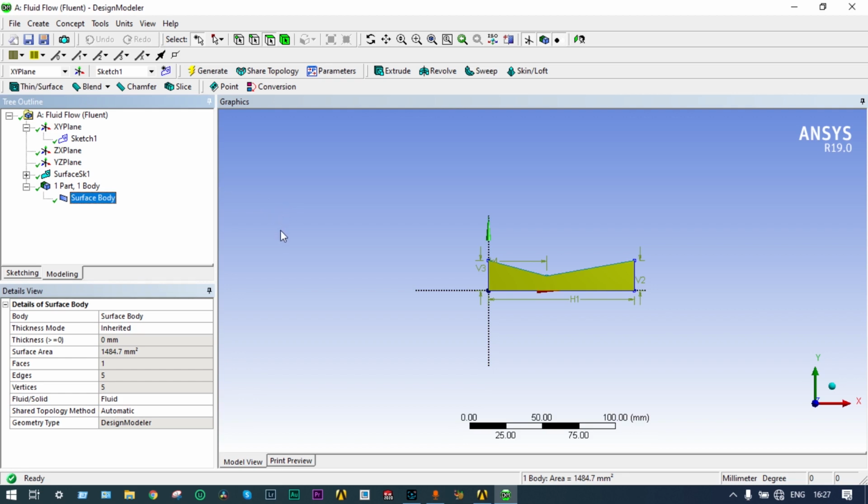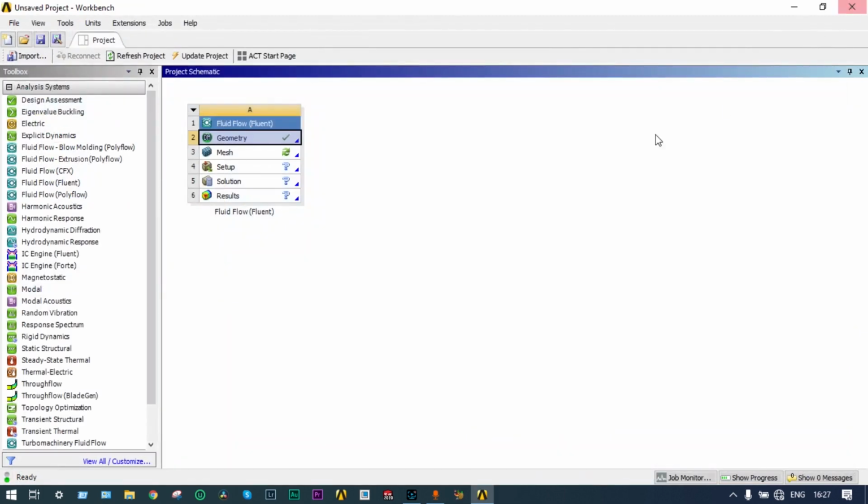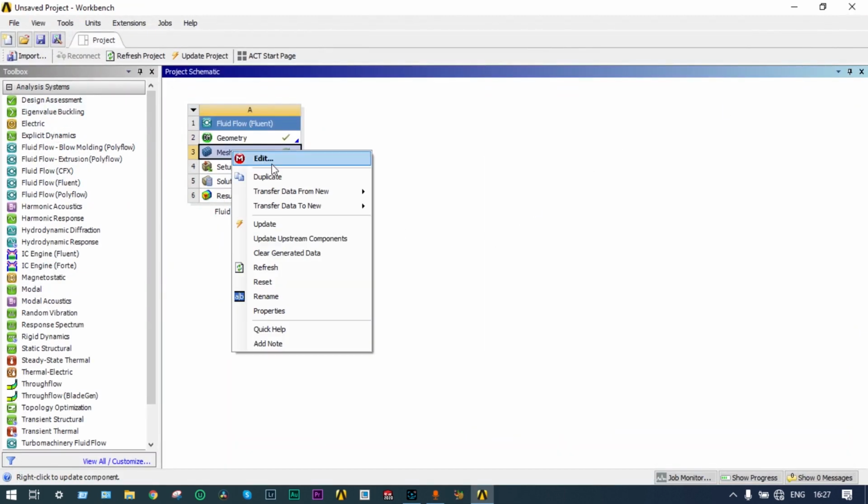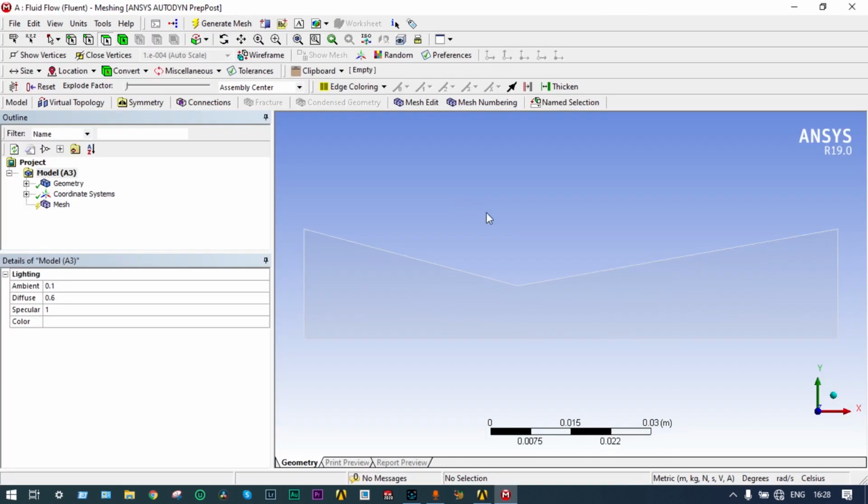Okay. Now next part we have to go for meshing. Let's exit from there. Mesh, edit mesh. This is the drawing. Now before starting meshing, while providing input variables, we have to provide names to these different endpoints like entry, exit, etc. That naming can be provided. So we start from naming. As we are considering the edges, they can be selected from here. This one can be selected as point, this one for solid geometry, this is for plane. We have to select the edges from here.